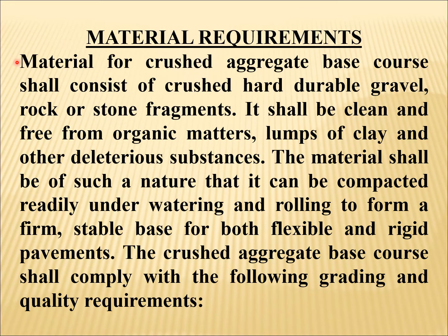Material requirements. Material for crushed aggregate base course shall consist of crushed hard durable gravel, rock or stone fragments. It shall be clean and free from organic matter, lumps of clay, and other deleterious substances. The material shall be of such a nature that it can be compacted readily under watering and rolling to form a firm, stable base for both flexible and rigid pavements. The crushed aggregate base course shall comply with the following grading and quality requirements.